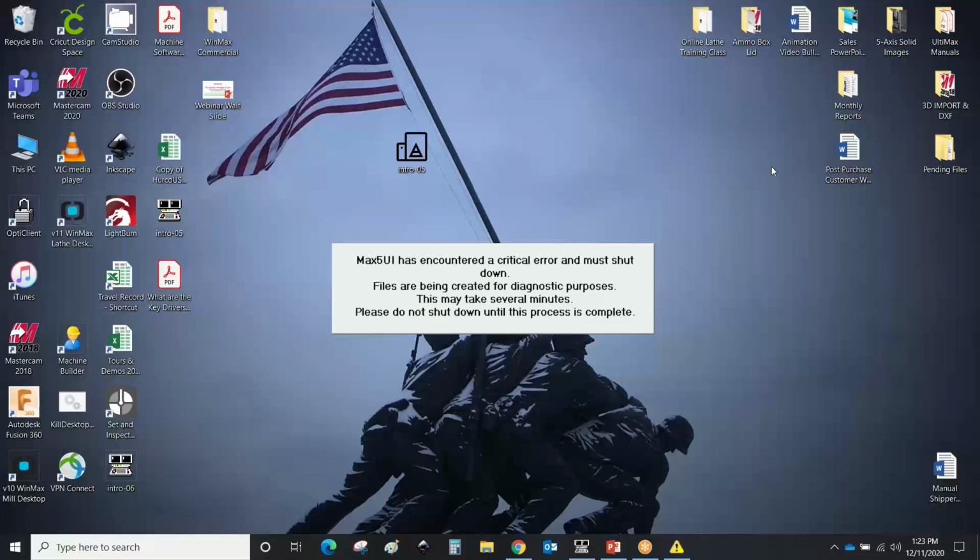So what I can't do, and what I was going to show you, but I'm going to have to reboot before my software will come back up, I believe. I'll try it here. But you would have to then take that to a CAM system or something to flip the part over. Because if I had saved it, the orientation is still just like it looked on the graphics, and Z positive, the top of the part, was the top of the part in that particular program. If I'm going to do secondary operations, I'm going to want to flip that over, so I would have to do that offline. We have requested ways to do that in the software, and someday we will be able to do that in graphics, but right now we cannot.